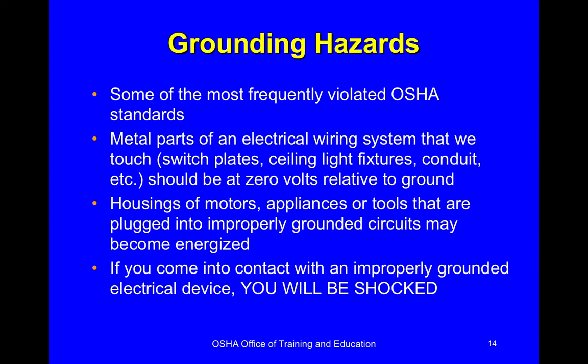Grounding hazards are pretty frequently cited as violations with OSHA. Remember, everything has to be grounded. You want to give electricity a path to take in case something else goes wrong. Okay? If you're holding on to tools and there is an electrical leak in there, remember, you lose muscle control. Usually you're going to lock onto it. So that means you lock onto the tool and you can't let go of it.